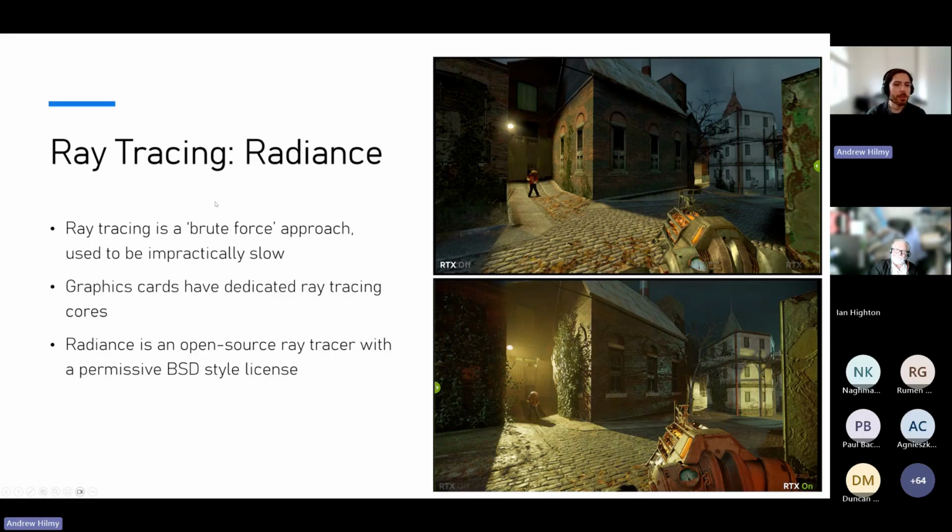So what we're thinking is we'll probably offer both and keep our radiosity solution, because our radiosity solution is still really good for diffuse. But the downside is the scalability. As you're scaling up with our current implementation, if you end up with really large geometries, the simulation time can increase quite rapidly. Whereas it seems as though with a ray tracing based approach with these graphics cards, which have hundreds of ray tracing cores, the scaling is much better. So it'll be really good for really big models.